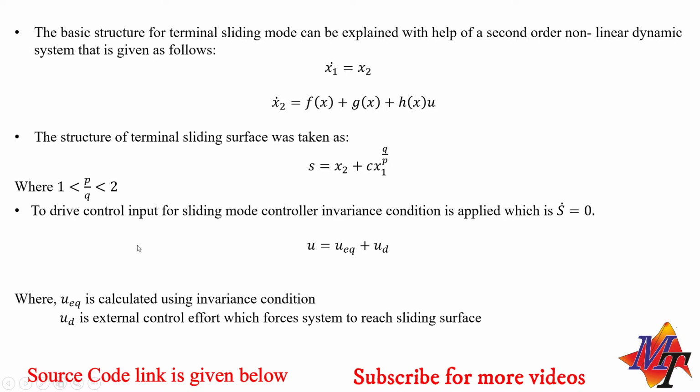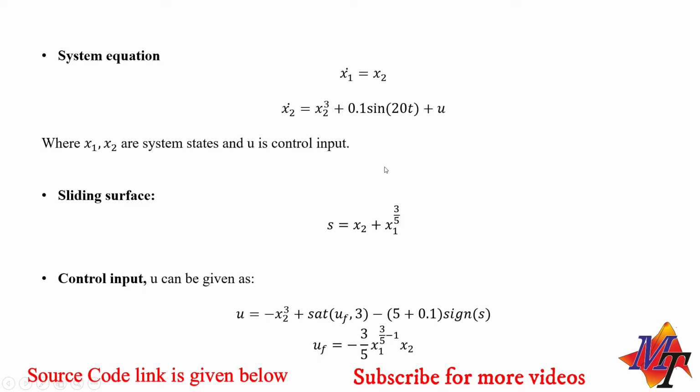Now to derive the control input for the sliding mode approach, we need to have two parts, that is u d, the external control effort, that is usually minus k sin s, and u equivalent, which is calculated by differentiating this sliding surface and equating it to 0. Now for this video, we have taken an example of second order non-linear dynamics where the system equation is x1 dot equals x2 and x2 dot is x2 cube plus 0.1 sin 20t plus u, where u is a control input and x1, x2 are system states that need to reach their respective equilibrium point.